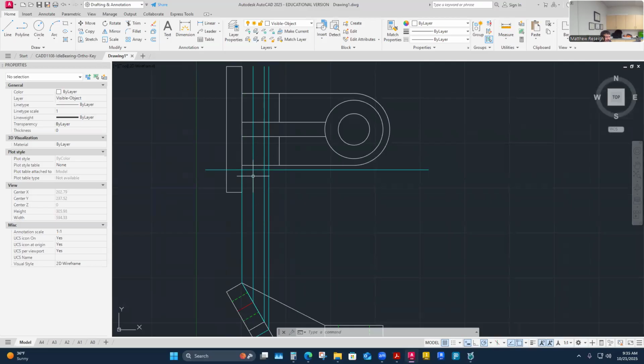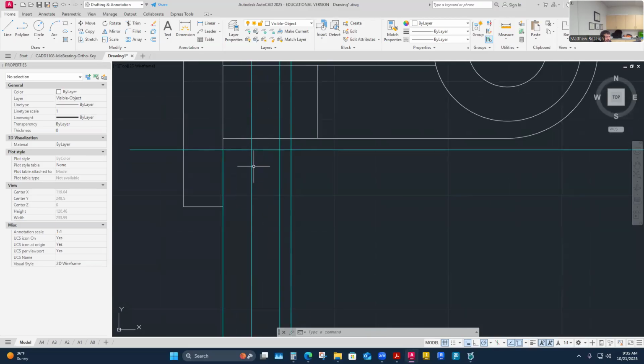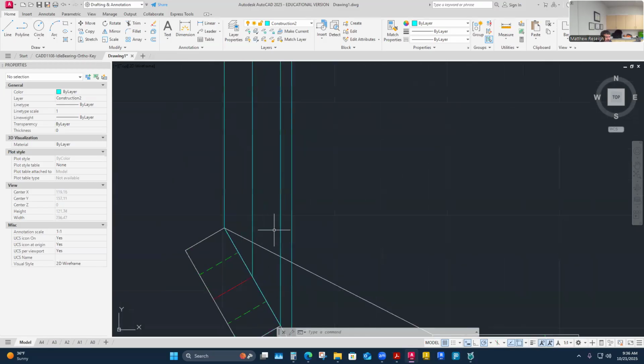The other axis is going to be, looking down on this, I'm going to actually see its true length here. So it will measure 50 millimeter across this way and only 25 millimeter this way. So I just need to have some points to pull that to. And so I might project a little bit more work here, some kind of a boundary, just projecting this across, arbitrary. So this is going to be the major radius of this ellipse. That's 25 and then 50. And then this is going to be the minor radius of the ellipse here, which is going to be half of whatever this is. Half of 25 is 12 and a half.